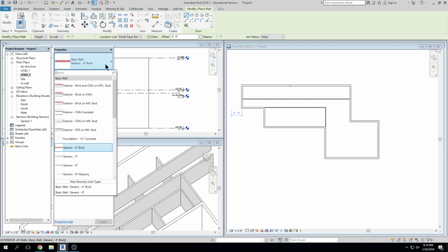We do have, let me just say this, comparing this to AutoCAD, right? In AutoCAD, to define and place architectural elements, you use layers that are called AE-wall, AE meaning architectural, right? And a structural engineer will use layers like SE-wall, right? So you are essentially placing all of these things on an AE, or architectural, discipline definition.